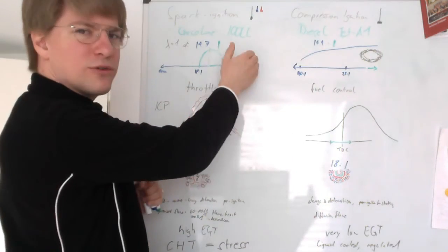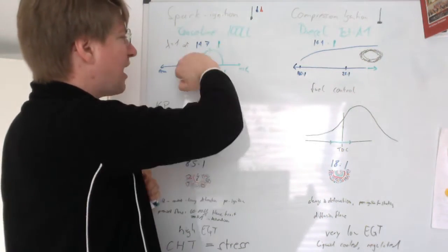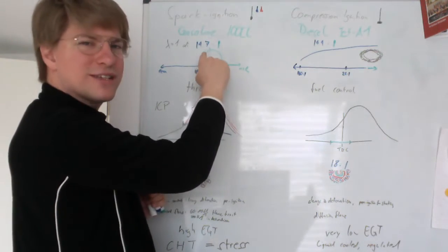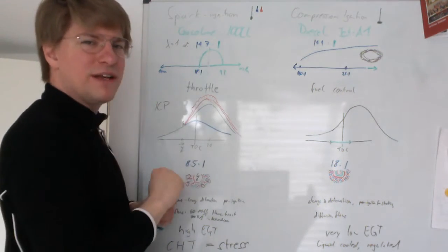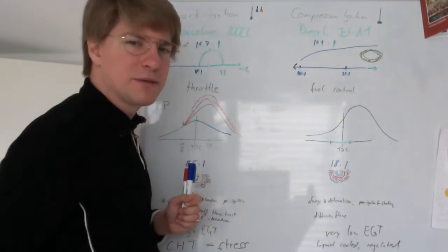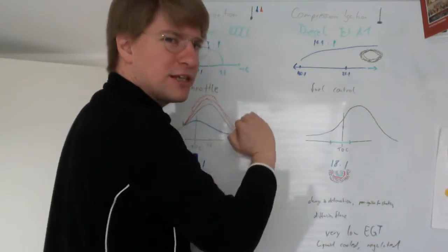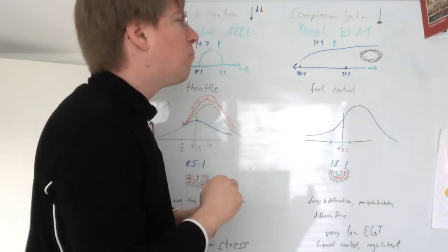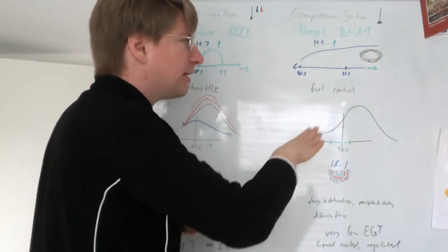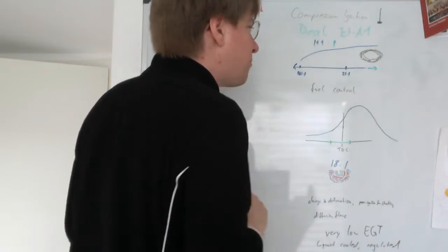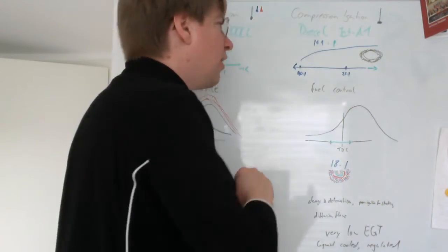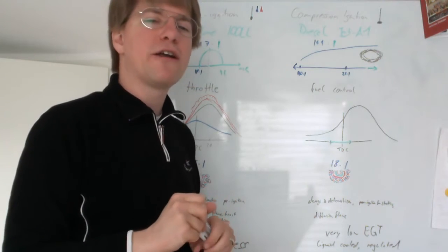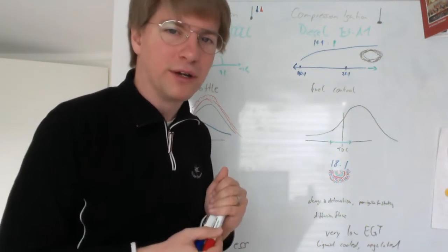So if you compare those two curves, you see that the gasoline mixture curve drops off extremely fast on the lean side of the optimal mixture, whereas the diesel mixture curve is a very nice slope, very controllable. If you run rich of about 25 to 1, what starts to happen is you get soot. Your engine is going to produce a lot of smoke.